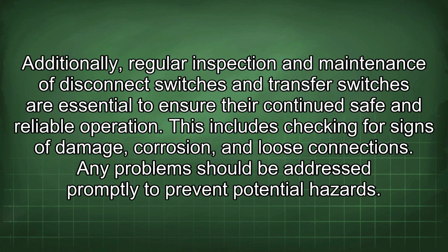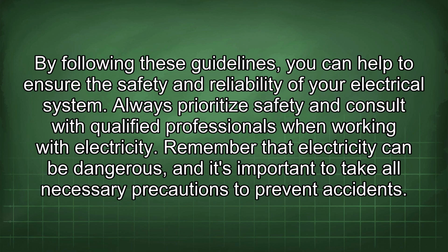Additionally, regular inspection and maintenance of disconnect switches and transfer switches are essential to ensure their continued safe and reliable operation. This includes checking for signs of damage, corrosion, and loose connections. Any problems should be addressed promptly to prevent potential hazards. By following these guidelines, you can help to ensure the safety and reliability of your electrical system. Always prioritize safety and consult with qualified professionals when working with electricity.